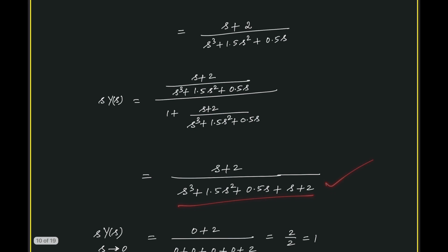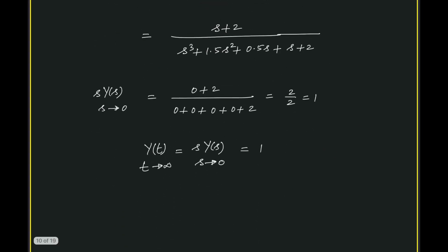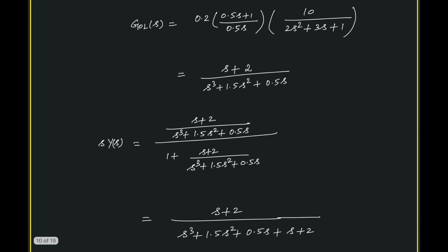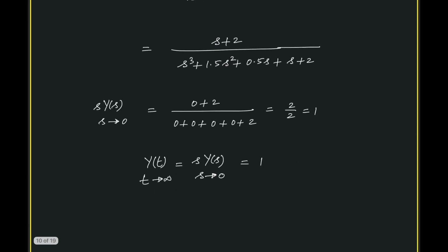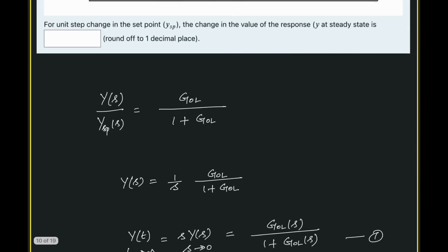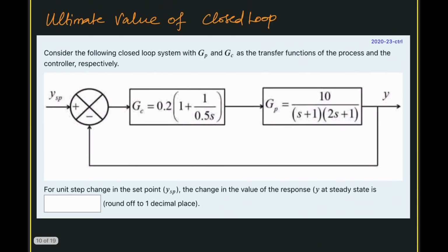This is because of the integral action. The integral action leads to eliminating the offset, but it is increasing the order. Thereby the response is getting a little slower than the original system response. Originally it is second order, now it is turning to third order because a lag is getting introduced. Overall we have reached a zero offset closed loop system.